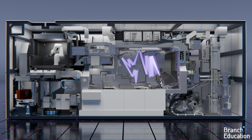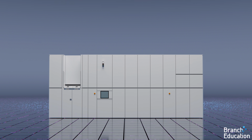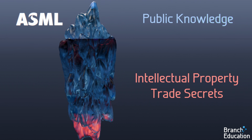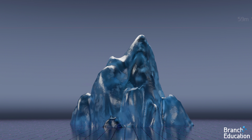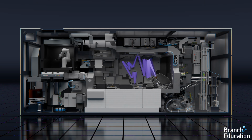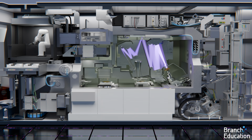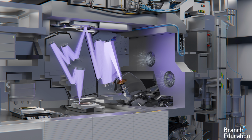We want to take a short detour and mention that this has been a rather challenging video to make, simply because there's a mountain of science and engineering inside these machines built by ASML, and this video only explores the tip of the iceberg. Essentially, a lot of the details had to be cut in order to keep this video a manageable length. For example, EUV light is incredibly difficult to work with because it's absorbed by atmospheric molecules, and therefore the entire light path and wafer carrier stage is connected to vacuum pumps which remove all the air.